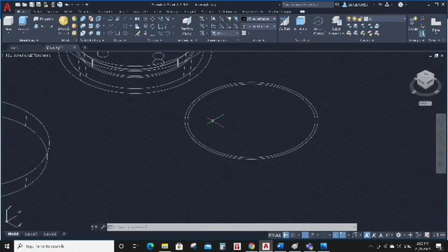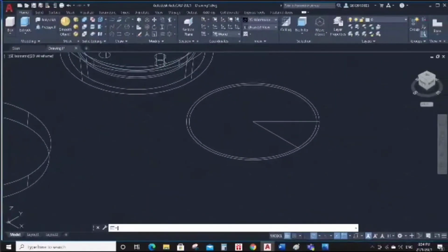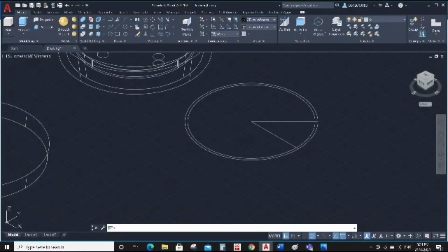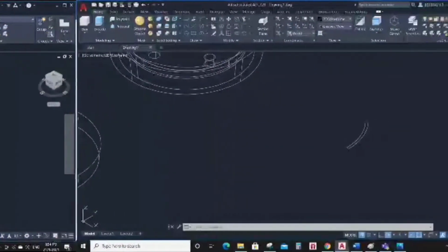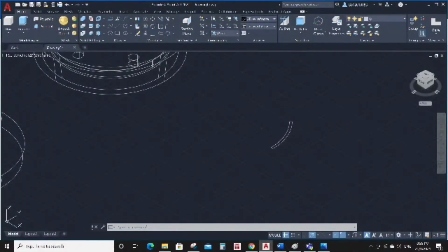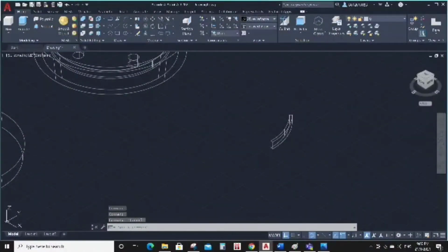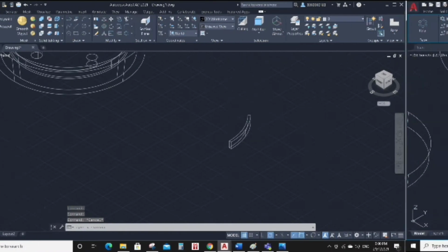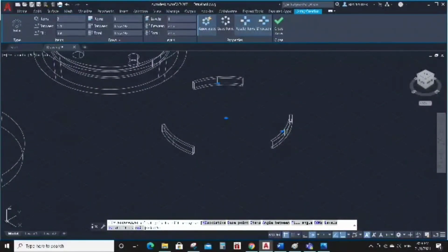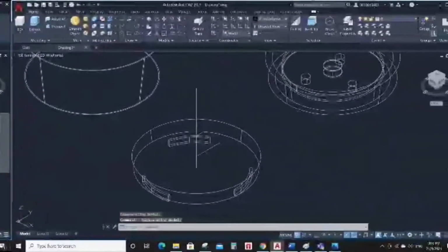This is the part to make the rice cooker fit. Firstly, I use circles at radius 120 mm and 115 mm. Then I made a straight line and another line at 45 degrees. Then I trim the line. After that, I use the command join on the lines. Then I use the command extrude to make it a 3D object, and the height is 15 mm. I use the command polar array for the same distance and make it into 3. Then I move it to the bottom section.